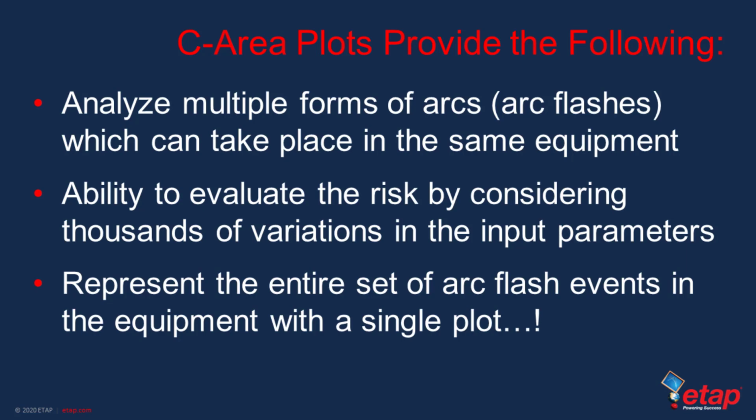Very rarely will an arc flash within an equipment behave exactly like what was used in the test setup in the actual laboratory conditions. Therefore, for any one location, it is likely that the arc could take on different forms, and thus it is necessary to consider how each form of the arc could impact the response time of the upstream protective devices, or the opening time of the upstream protective device.